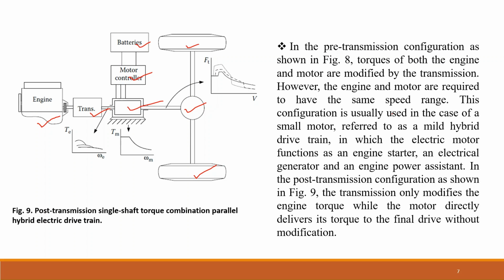However, in the post-transmission case shown in this figure, the transmission is there before the motor. So this transmission only modifies the engine torque, while the motor directly delivers its torque to the final drive shaft without any modification. So both of these configurations are needed. Why pre-transmission is needed and why post-transmission is needed is well explained. Now coming to